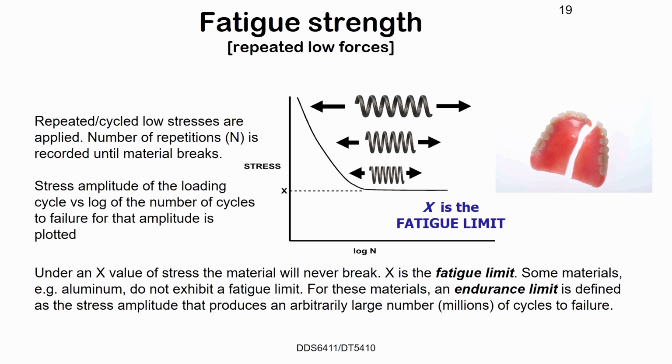But some materials do not have a fatigue limit. For metals, aluminum, or aluminium, where I came from, it doesn't have a fatigue limit. So any stress, whatever the amplitude, will cause fatigue eventually. For these materials, we will put on an arbitrary large number of cycles for design.